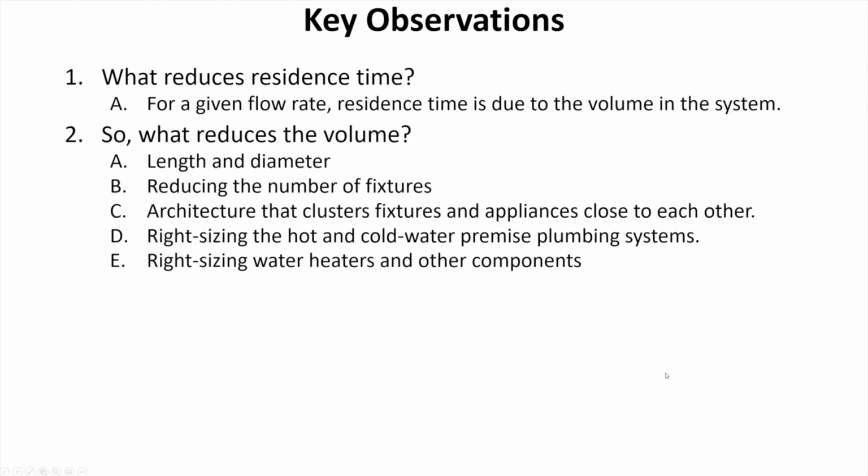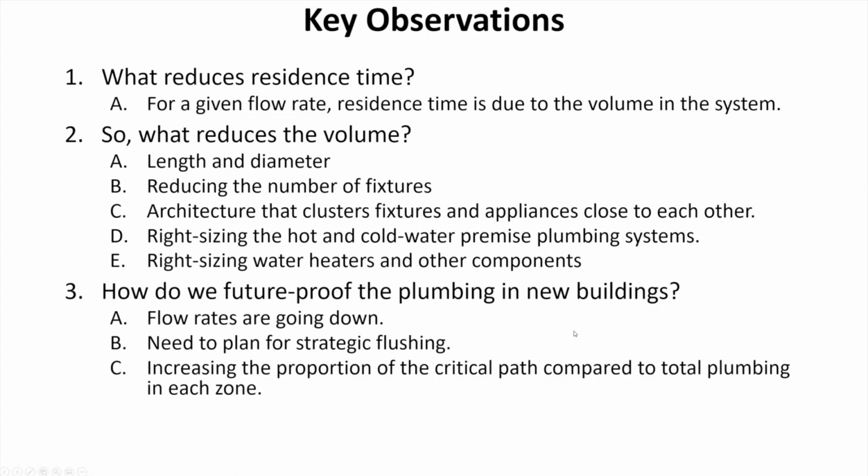So what reduces the volume? Length and diameter, reducing the number of fixtures, architecture that clusters fixtures and appliances close to each other, right-sizing the premise plumbing and the water heaters and other components. What I want to talk about for a minute here, under what reduces volume, is the number of fixtures.